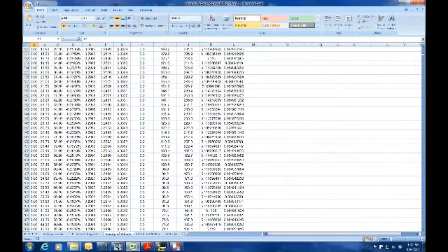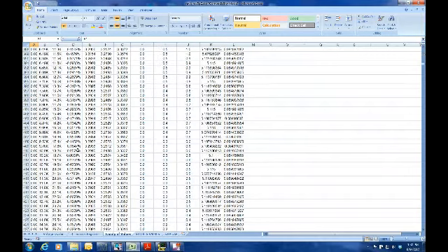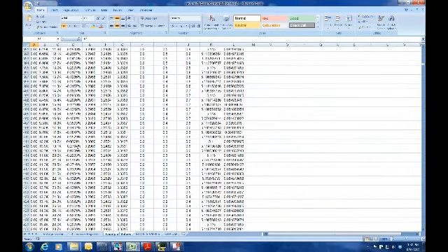And then we come down here to the area that you particularly care about, and see if there's anything out there that'll work that you have in stock or that you're willing to buy. So here again we have the 10k and the 18.2, but it has a little bit of tolerance to it. The output voltage is a little bit off versus the 10.2 and the 18.7.